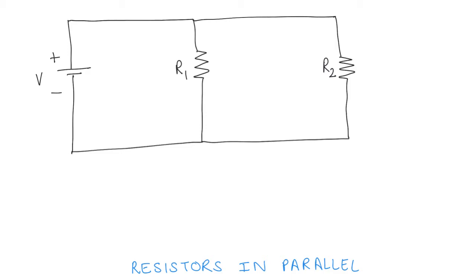So what is the voltage across R2, let's say? If you want to look at the voltage, you need to know what the voltage at this point is and what the voltage at this point is, right? So what's the voltage at this point? Let's call it A1. What's the voltage at A1? It's the same voltage which is applied here, A, because A and A prime are connected just by a wire, and this wire denotes an equipotential line. So the potential at A1 and A2 are the same.